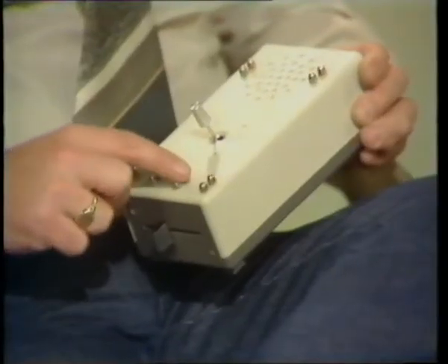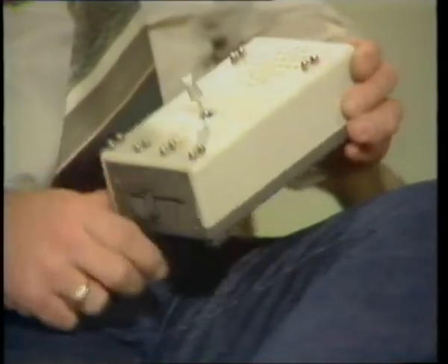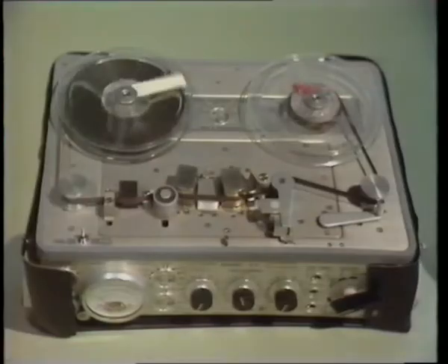Well, normally in electronics, we do our best to get rid of noise. It's a nuisance. But in speech synthesis, we put it to good use in generating the unvoiced sounds that Mike was talking about, the sh, the s, and the fs. So by passing white noise through filters which attenuate the right frequencies, we can shape or mold this flat spectrum into the forms that Mike had just now. I've got 3 on the chatterbox, for instance. But no matter how I practice trying to make it talk, I'll never get as good as this.